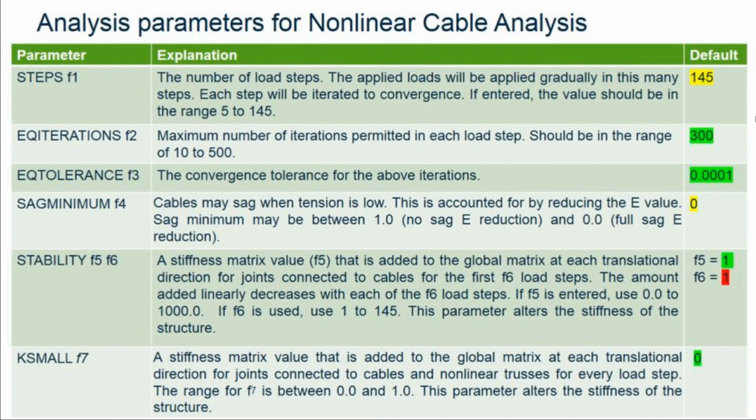Whereas for small structures, leave it at the default 145. That's why I highlighted it in yellow, because for most of the models you don't have to change it. Leave it at the default, except for huge models where you need to reduce it to a lower value to reduce the analysis time.